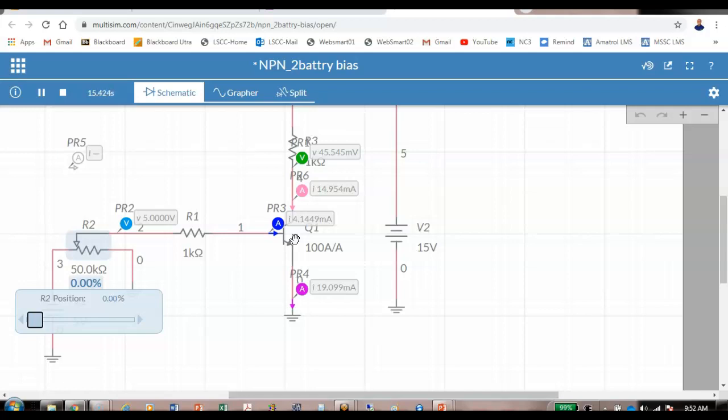If we measure the applied voltage, which we will, then we say this is in cutoff. If it's somewhere between the applied voltage across the transistor and 0 volts, or less than 1 volt, it's going to be in what we call the active region. When it's in the active region, I could literally put a varying signal into this, and then the output would perform proportionally.